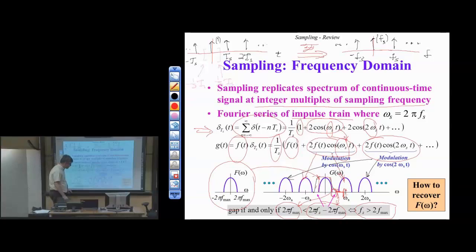No, what I meant was, for instance, let's say our pass band goes, we want 0 to 10 kilohertz. Would we be okay if we tried sampling only up to 9.5 kilohertz and we allowed that extra half kilohertz to let it roll off? Yeah, that's exactly what we might do in practice. So if I know that I want to capture from 0 to 10 hertz, let's say I sample at 20 hertz.